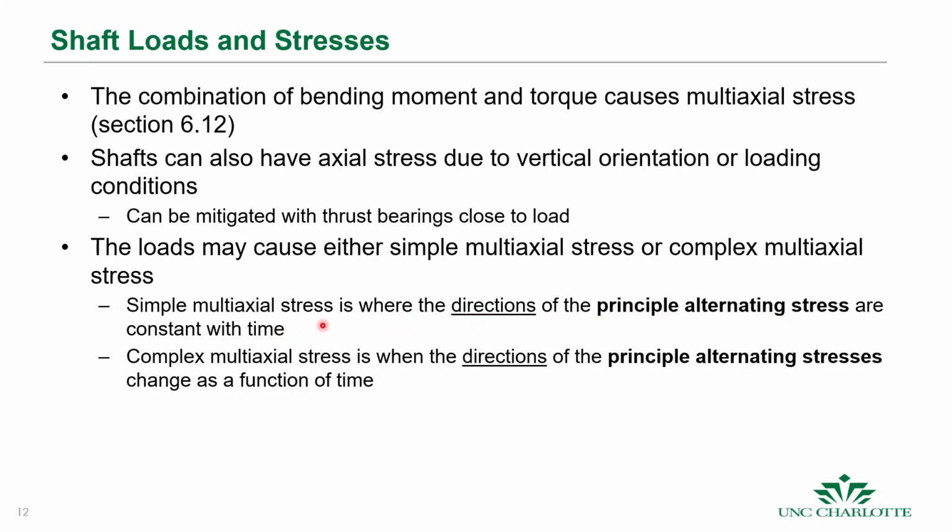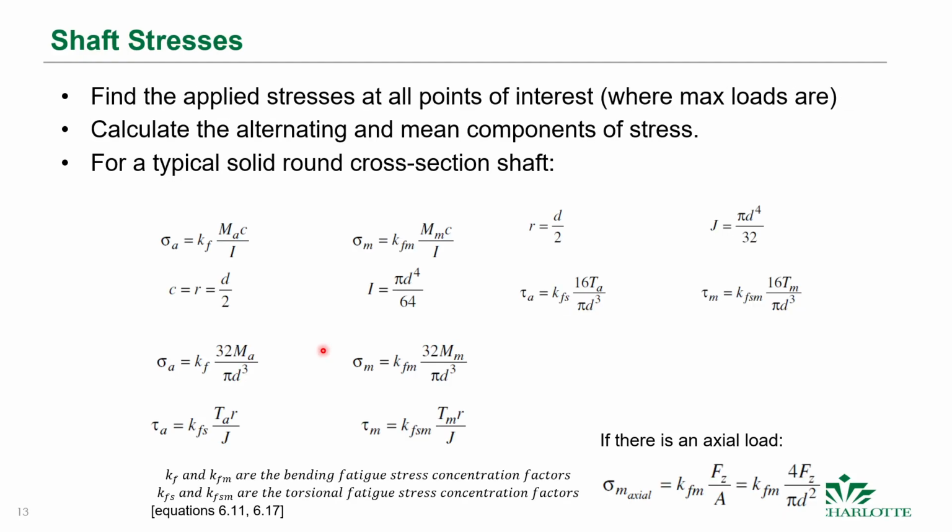If you have a complex multi-axial stress, then the directions of the principal stresses are changing as a function of time. This might be something where, as it rotates, the loading is a function of the rotation versus a function of the rotation relative to an applied load. So it's important to understand the state of stress, whether it's simple or complex multi-axial stress, when we get into our design.